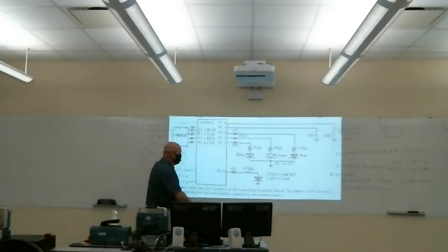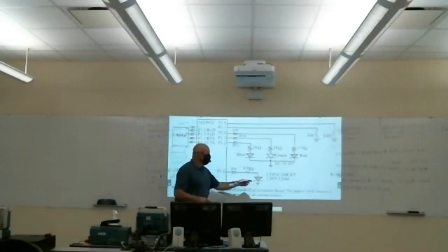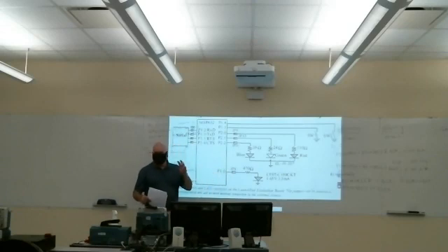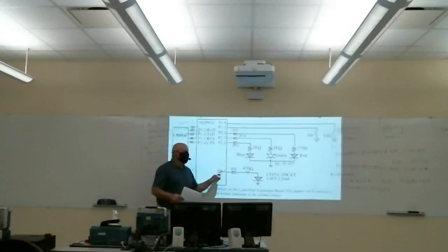And so, for example, this is the red LED, this is the tricolor LED, but if we wanted to turn on the red LED, we'd have to set pin 0 on port 1, the general purpose I/O function. Again, that's the default.